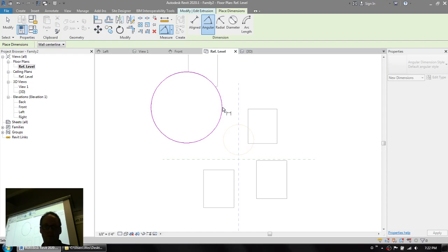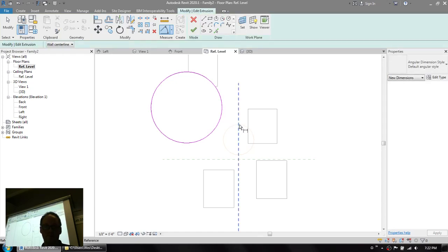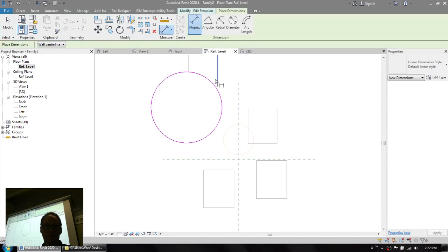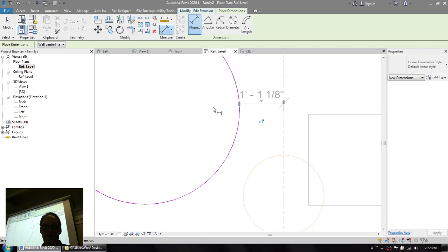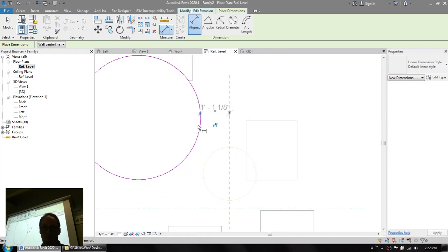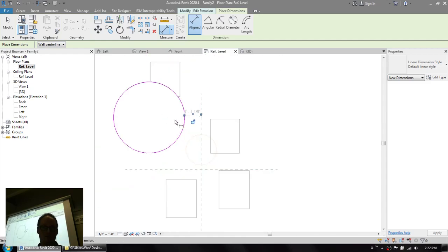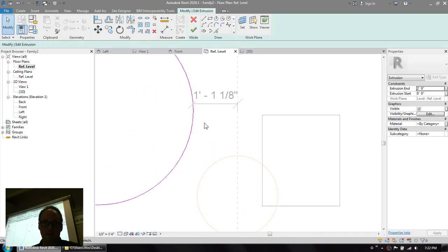So if I first choose a quadrant, you just click on it. And why isn't it placed? Oh, I used an angular dimension, that's why. So it's using a line dimension. So pick a quadrant. So you can run the geometry to the, now you'll notice here that I'm editing a circle, so it's already existing.